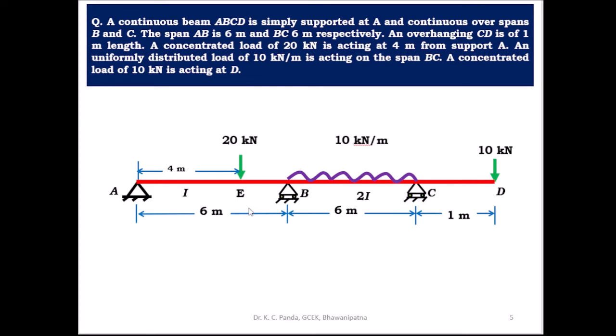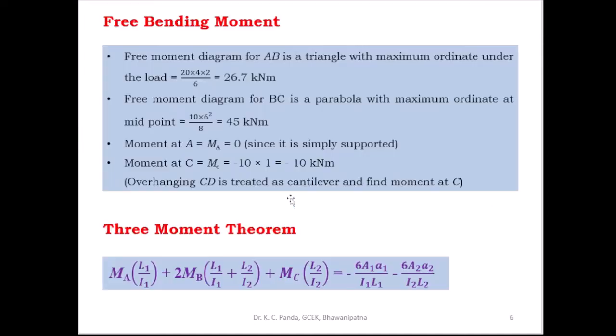First, apply the Clapeyron theorem of three moments to the spans AB and BC, two consecutive spans. Draw the free bending moment diagram by treating each span as a simply supported beam. So first you have to draw the free bending moment diagram, or simply supported bending moment diagram.